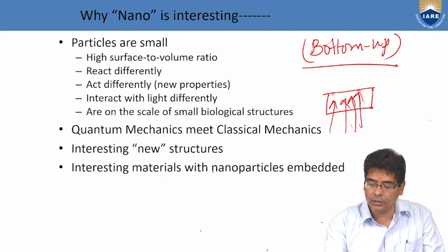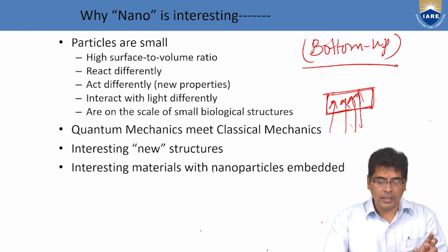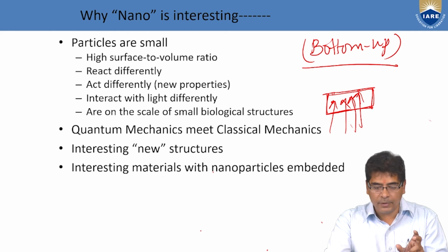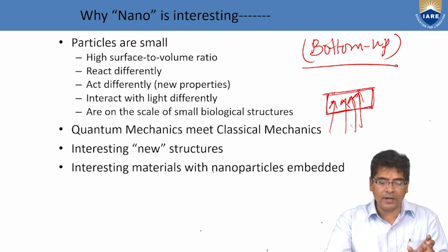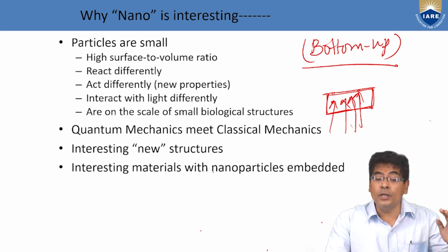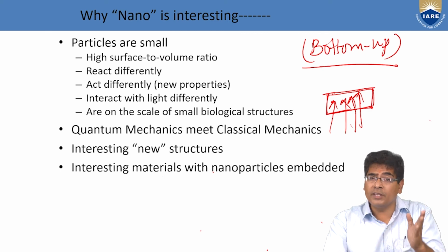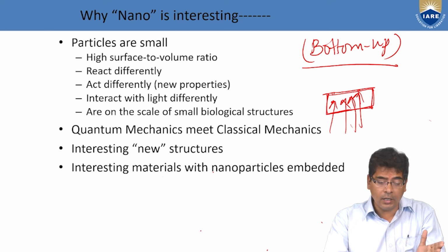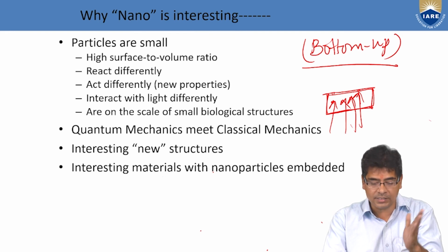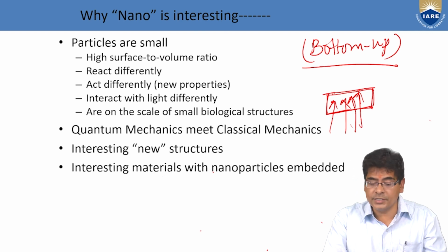if you deposit some solution on this substrate, we have to keep that substrate until it gets dried. That means it should get into the form of a gel. During this gelation time, the material gradually loses its fluidity and undergoes a transition from viscous liquid state to elastic solid state. That means there is a phase transition from a liquid state to a solid state.